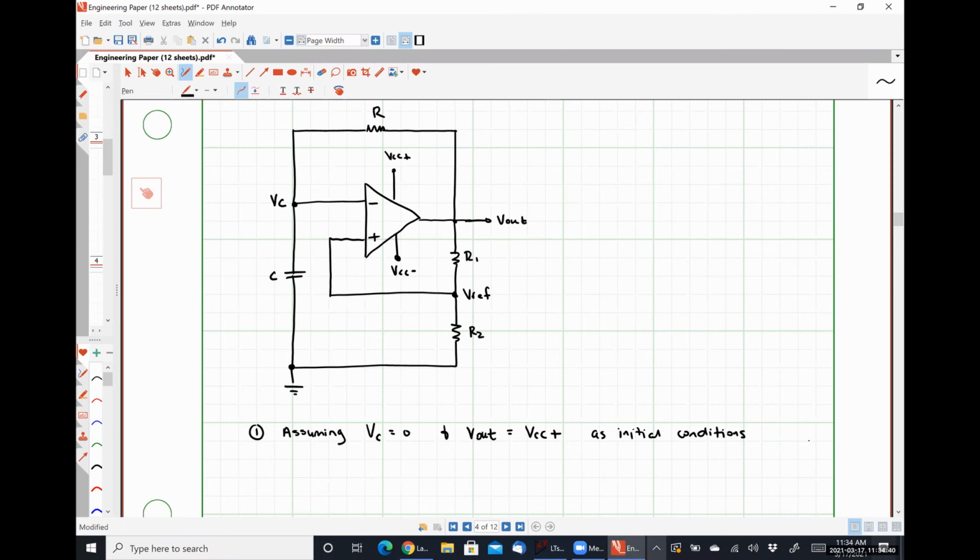So along the other direction, we started off saying that the voltage drop over the capacitor started as 0 volts. If V out is positive, that means there is a voltage drop over that resistor R, which means current must be flowing through it, right? That current can't branch off and flow into the inverting input terminal.